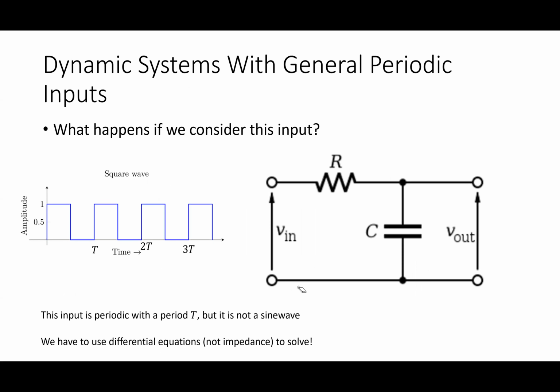So what happens if I have this? This is what I would call an AC input as well. This is a pretty common thing. Like I said, if I look at what goes on in a memory chip, this is pretty similar to what it is. I have a Vn, which is a square wave. This guy I'm going to call a square wave, or really what I think of as a clock signal. So if I have that square wave going into this circuit, this guy is periodic.